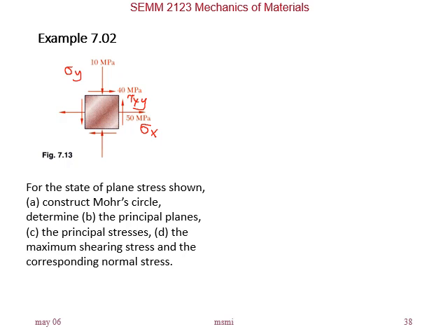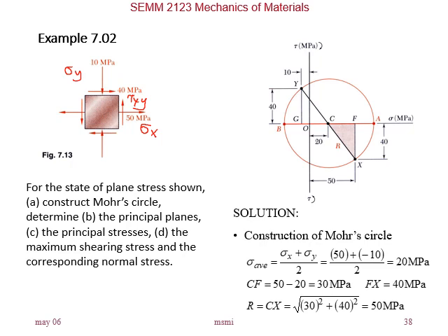So this is the same example as before. So you draw Mohr circle. What you then draw is, first you plot point x. Point x is 50, 40. It's shown here. That is sigma x. That is tau xy. Sorry, it's counterclockwise. So it's positive downwards or counterclockwise. See the arrow here? The arrow shows direction is counterclockwise. Right? So that gives you point x.